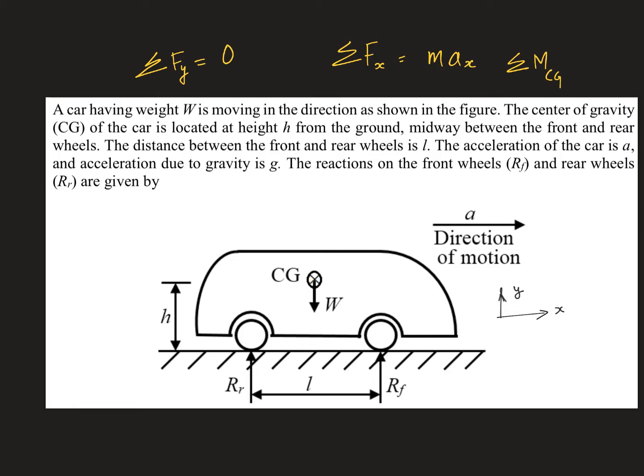There are a lot of external forces, so list out the external forces, then compute the moment about the CG. If I sum it up, then I should get 0 here. This particular equation comes from the fact that our automobile, the car, is not rotating. So we have three different equations which govern the motion of this particular system.